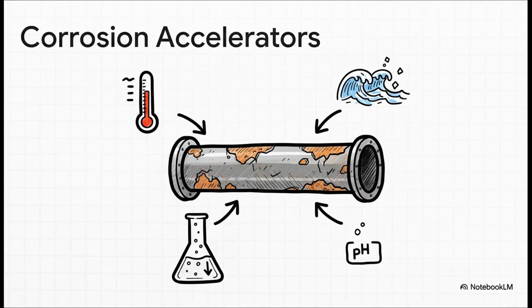And of course, it's not just about the metals. The environment they're in plays a huge role. Think of things like heat, salt in the water, or the pH level. They're all accelerators. They just speed up the whole chemical reaction, turning a bad situation into a total disaster.